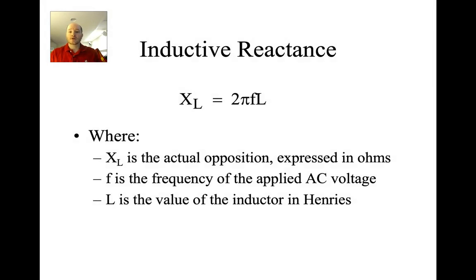Okay, so here's what is happening. Here is our formula, and this is a formula we're going to be using for the next, oh boy, four or five weeks at least: X of L. Go ahead and write that one down somewhere. You'll definitely need it for the lab. The formula is 2 pi F L.